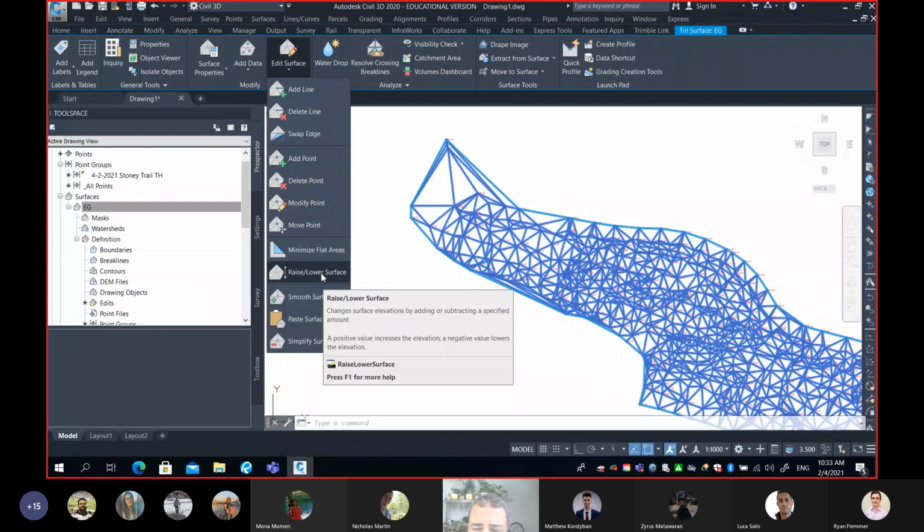Can we do that mathematically or on my software? Yes, you can. Because once you finish all your survey and you have a surface, you look at your geotechnical report where it says you have a topsoil of, let's say, 1 foot. So what can you do? Can anybody help me? What can you do to start your volume calculation, cut and fill, after you remove your topsoil?